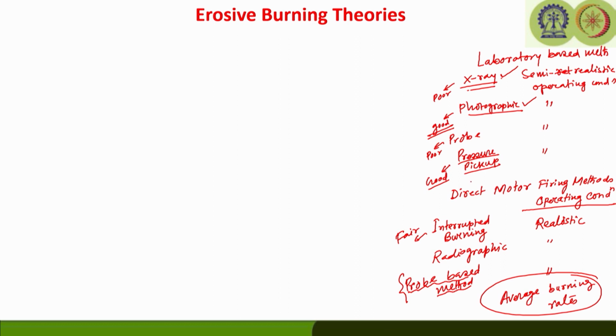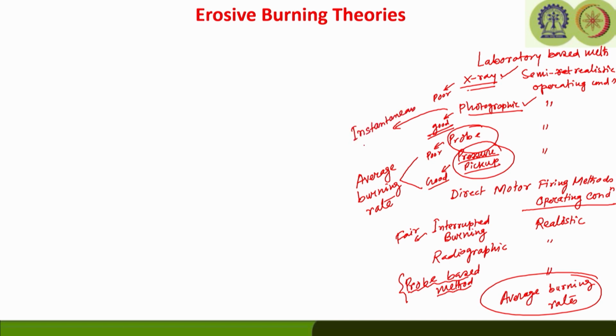Same thing we can say about this pressure pickup probe based method. They are also going to give the average burning rate. The photographic based method is going to give us instantaneous burning. As we can see, it is directly filming the burning event. So, we can expect that this is going to give the instantaneous burning rates,